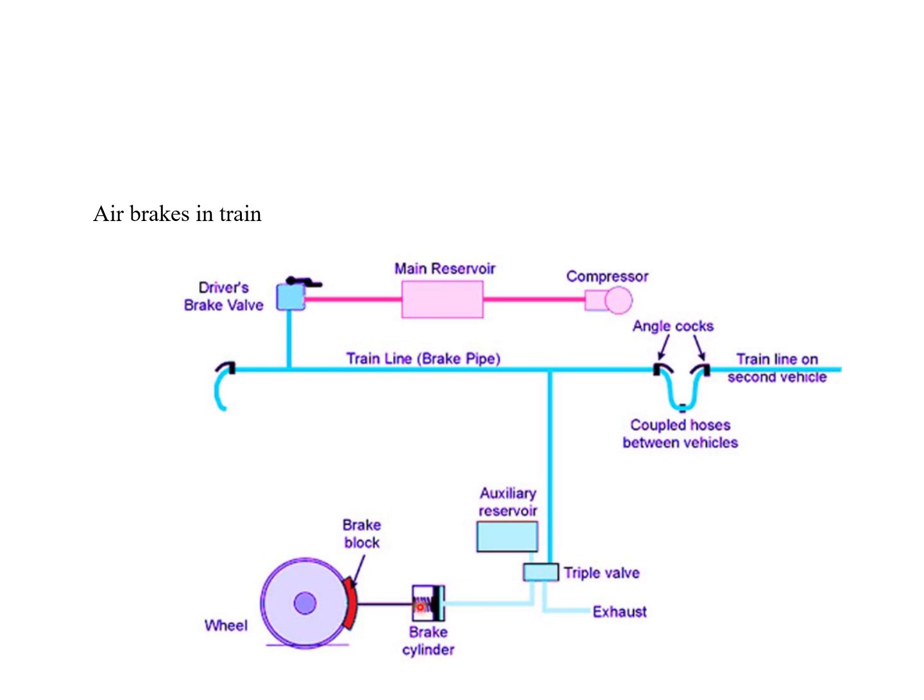The brake cylinder pushes the brake block against the wheel, creating friction to slow the train. When the brakes are released, the air is exhausted, allowing free movement. This system ensures uniform braking, automatic emergency stops in case of pressure loss, and reliable operation across long distances.